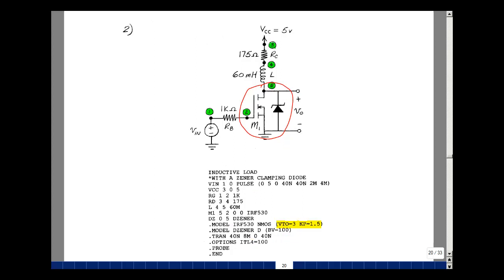When I ran the simulation, I had convergence problems. And what the SPICE program does is it takes a number of iterations during transient analysis, and if it can't find an answer, it quits. This goes back to the early days of computing, when computing wasn't for free. You had to pay for it per second. They built in essentially a safeguard to prevent burning up all of your account money.